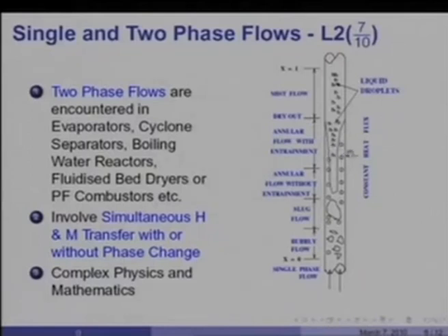If you continue to heat further, a situation is reached where nowhere in the cross section any liquid water is found, and you essentially have the tube in contact with water vapor only. Now, as a rule, the magnitude of the heat transfer coefficient in gases and vapors is much lower than in liquids.